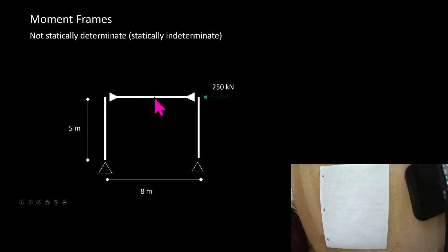Well, the reason it doesn't fall over is because we have moment connections here. Most tables and chairs that you see built don't have braces across here because we rely on a moment connection right here. So we're going to do the same thing we did for our braced frame using method of sections, knowing that there must be internal forces stopping this from flying off into space so that this reaction can get to our reaction points over here.